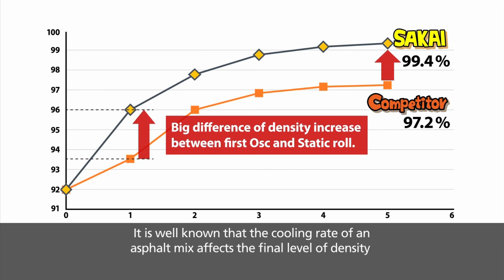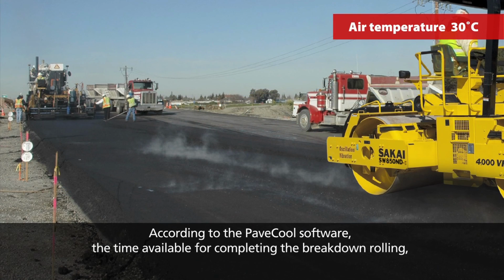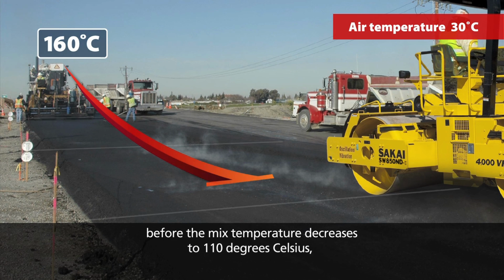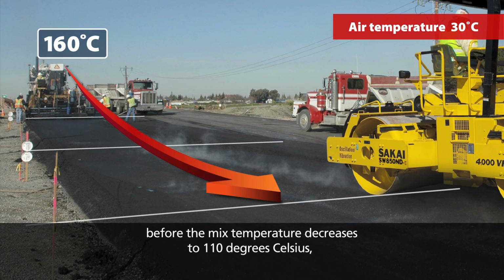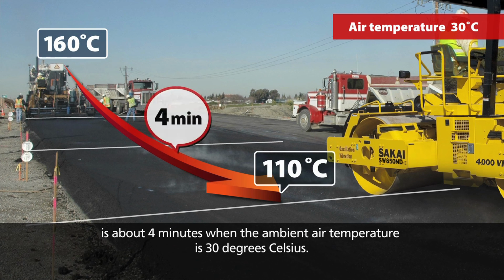It is well known that the cooling rate of an asphalt mix affects the final level of density that can be obtained. According to the PaveCool software, the time available for completing the breakdown rolling before the mix temperature decreases to 110 degrees Celsius is about 4 minutes when the ambient air temperature is 30 degrees Celsius.